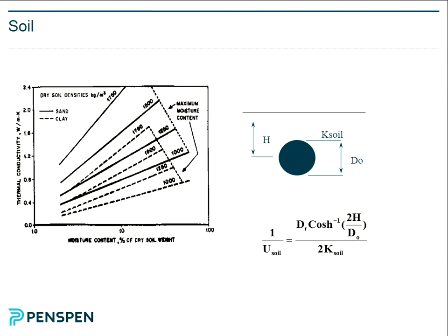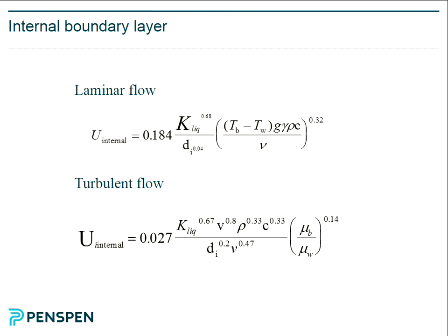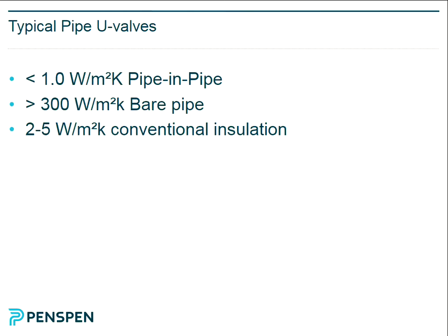Pipe-in-pipe systems have always been a challenge for offshore pipelines. The main reason why is because you have to come up with some way of making up a field joint, some way of joining a pipe-in-pipe system together. And there are different systems by different vendors, with different installation contractors. This is one where they bring the pipe-in-pipe down to one single weld. This is the double pipe lamination system, or DPIS, for Snamprogetti. But again, you could potentially lose a lot of heat in the joint here.